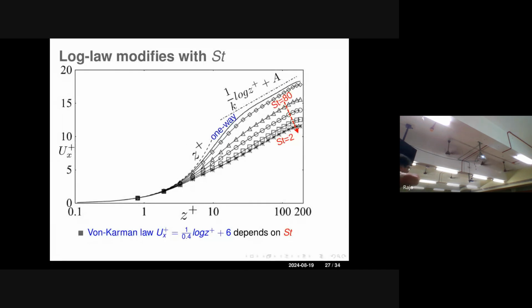So now coming back to these results. A turbulent channel with Re tau, right now we are showing something like 180. Particles are suspended, some 10 power 7 particles. The inlet condition itself is turbulent, it's not developing. You already have a synthetic turbulence forcing and turbulence really goes out of the system. So what we are looking at is the wall-normal coordinates. This is the box, flow comes, flow leaves, particles are continuously spread from the inlet and they are going up and down, like the animation I have shown, I will play it again.